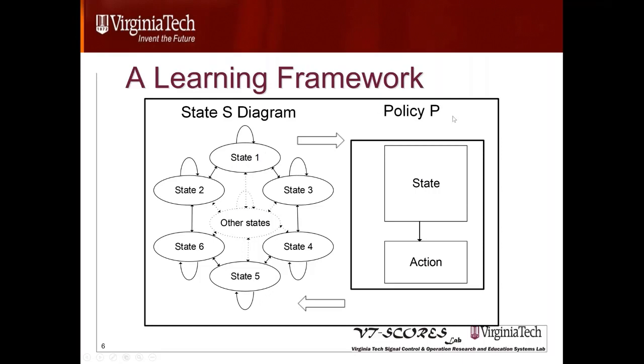But if I implement a new policy and say that for the next 15 minutes I want this road to stay red, I'm just closing the road for 15 minutes, and I'm doing the analysis for any period within those 15 minutes, then my system is going to stay in state red, and it's not going to transition to state green. So the policy is going to impact the state probability.